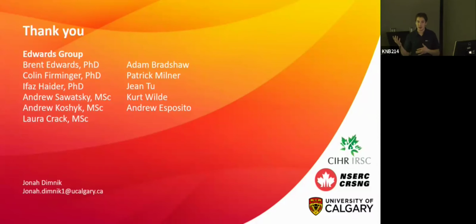So here we use a strain-based continuum damage model, but there are plenty of damage models that try to estimate that based on many different factors. So it becomes a pretty complicated phenomenon, but at the very base level, we're really just looking at the total area of the cracks and voids in comparison to the area that we're looking at. It's basically cracks and voids in the bone.